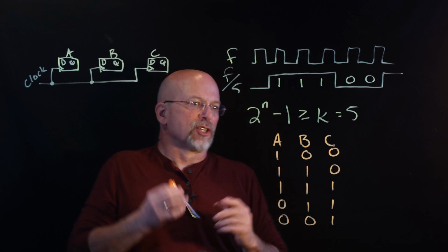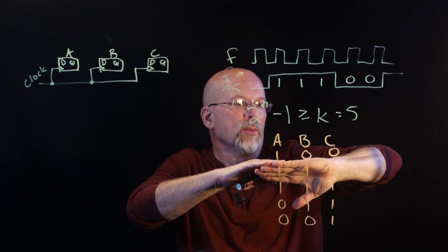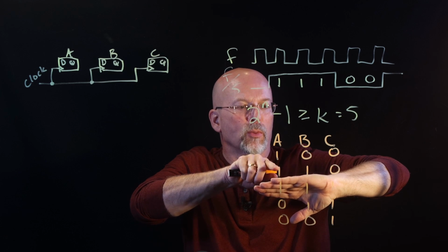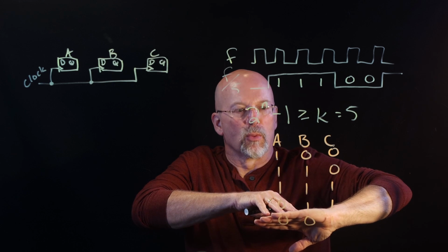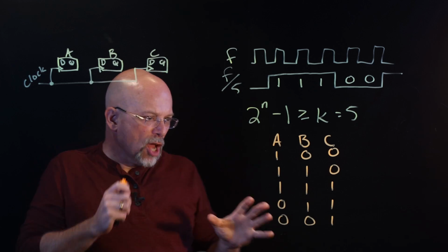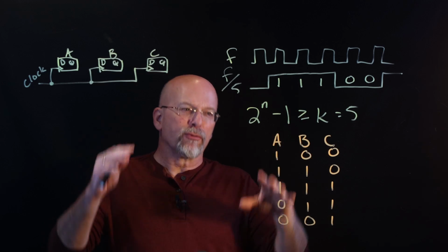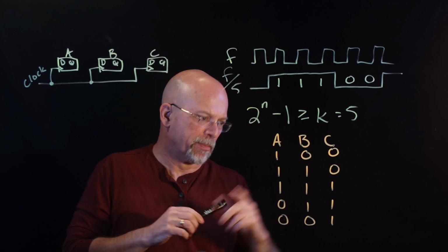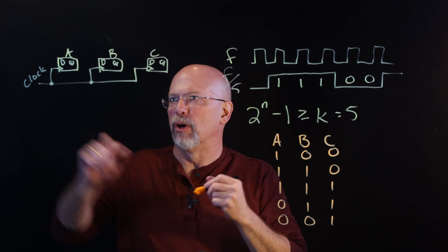All right. And so what's going to happen is at time 0, we'll have 1, 1, 0, 0 in those 3 flip-flops. We get a clock pulse, we'll get the next one, 1, 1, 0. Get a clock pulse, we'll get 1, 1, 1. Get a clock pulse, we'll get 0, 1, 1. Get a clock pulse, we'll get 0, 0, 1. Now, the important thing to note is that this particular sequence really doesn't have a beginning and an end. All you're looking for is to get this sequence going over and over again so that we get this divide by clock application.